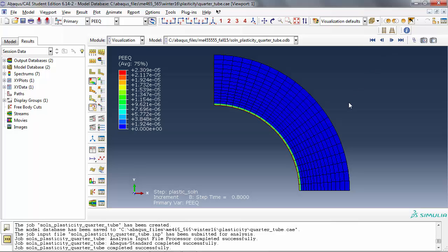Do you see what happened? In the 8th increment, 9th increment, plastic strain is going further in. 10th increment is where your plastic strain has finally finalized. And what is the magnitude of the plastic strain is given by these values. Think of it as a von Mises equivalent to plastic strain, meaning all the components of the plastic strain, not along radial or tangential or x and y directions, everything combined.